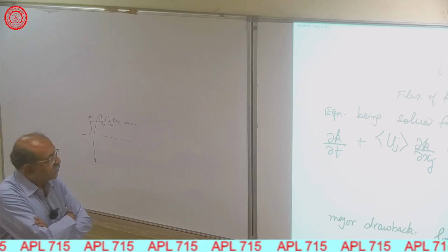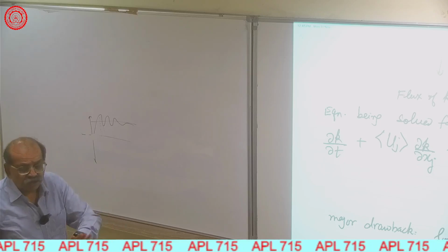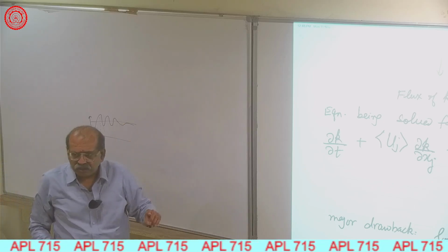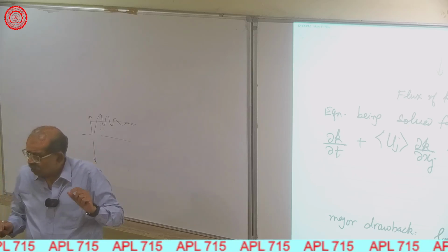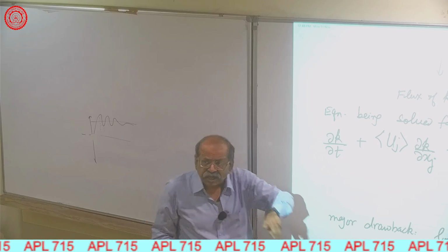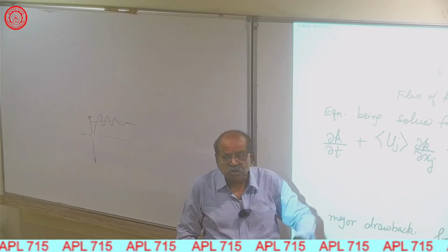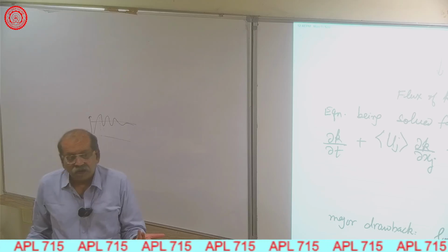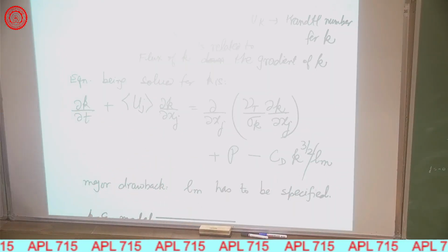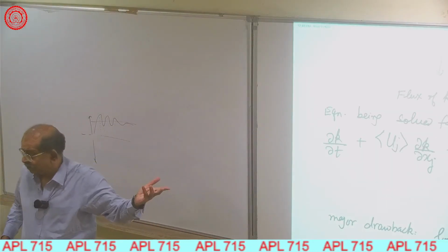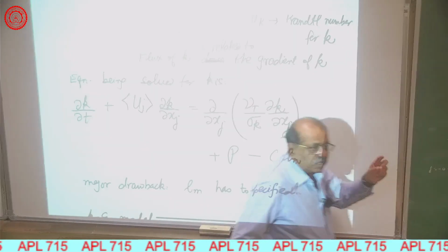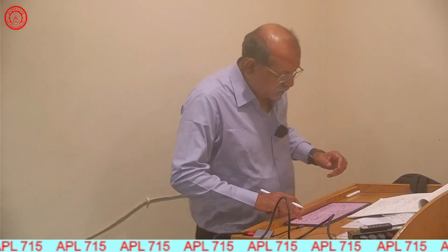No, I'm not saying how do you get the epsilon equation. What I'm saying is I'm solving this k equation. This is the k equation when I use it for the one equation model. Now when I use the k equation in the k epsilon model, do I make any changes to this or do I solve the same equation? Last term will be epsilon. Now I don't need to model epsilon here. So the last term will be replaced by epsilon. All other models have to stay. So when I solve the k equation in the k epsilon model, the last term will be replaced by epsilon.